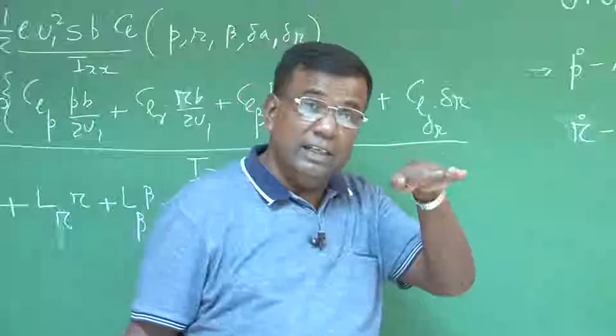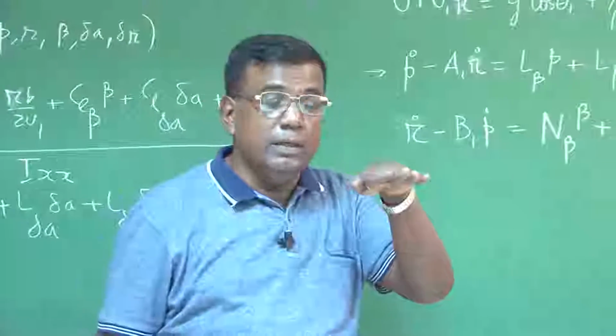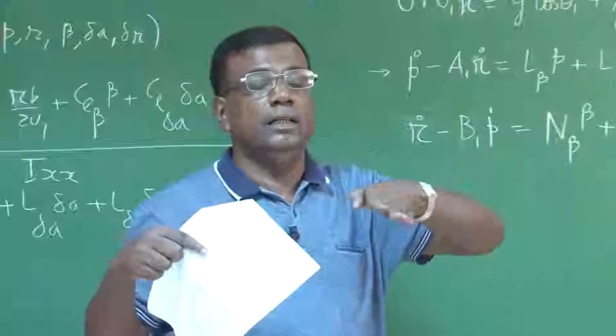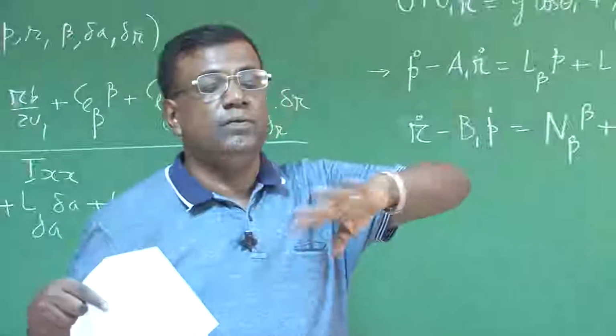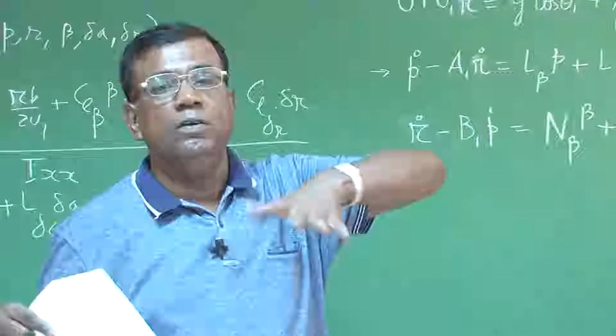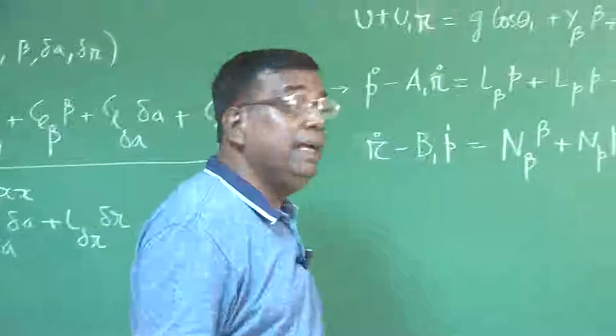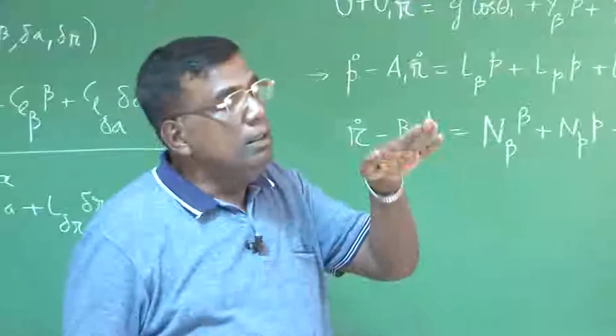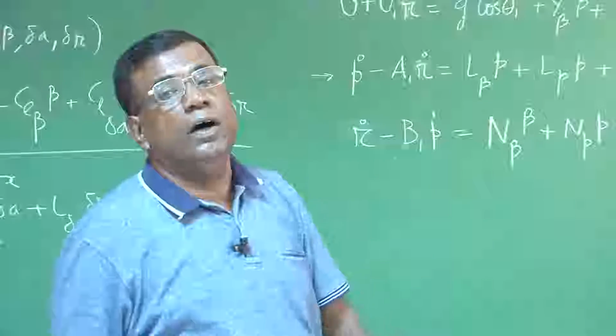Directional stability: if there is a wind like this, it will try to neutralize beta, it will turn like this. So, very, very sensitive. Your frequency will go on increasing, right. Like for the longitudinal case, if Cm alpha is more and more, the longitudinal natural frequency goes on increasing.